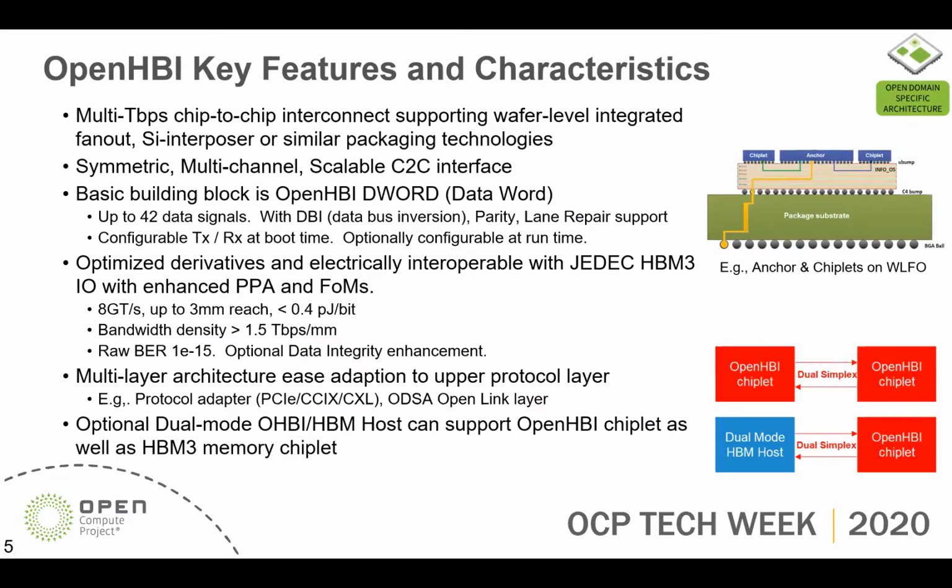So OpenHBI has several key features that come into play by leveraging JEDEC HBM as a foundation. First, we focus on enabling multi-terabit per second high-performance chip-to-chip interconnect, as we mentioned. We will be using an interposer for high-density interconnect, which can be a silicon interposer or wafer-level fan-out or similar. The interface is defined as a symmetric, multi-channel, scalable interface. By symmetric, it means that OpenHBI itself does not have the notion of master or subordinate, initiator or target. It is a symmetric transport that can be mapped to an upper layer, which will then determine how the